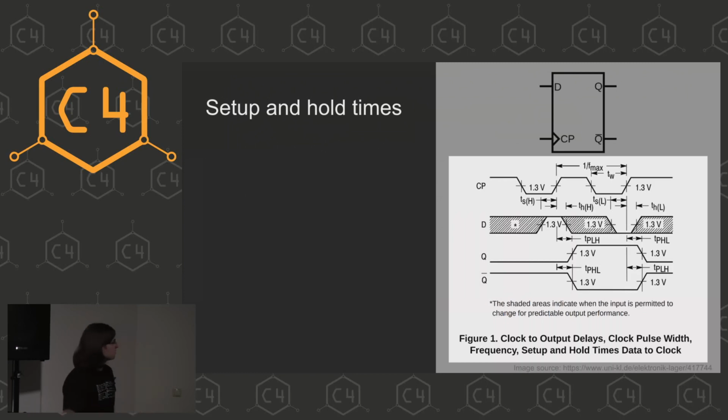And as I said, this flip-flop is edge triggered, which means every time we have a rising edge here in the clock, something will happen down here. So this happens two times, here and here. And if we look at the D pin, these shaded areas mean that it doesn't matter what this D pin is, because the flip-flop will only act on the rising edge of the clock.